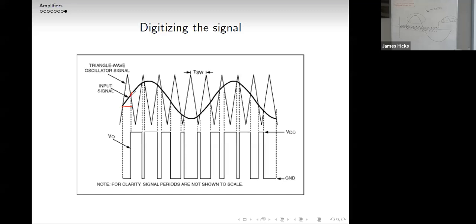But as soon as the triangular wave crosses with the input signal here, from this point over to here, my input signal is bigger than my triangular wave signal, so my comparator signal on the bottom goes high. And that just keeps going through the entire process. It works because the triangular wave has a much higher frequency than the input signal. It's kind of sampling your input signal.